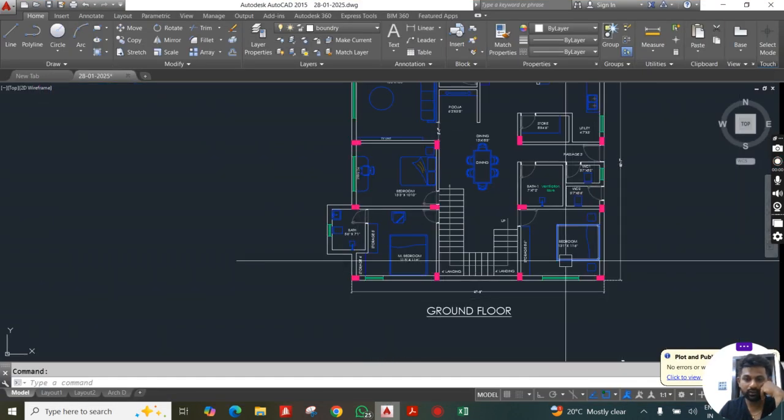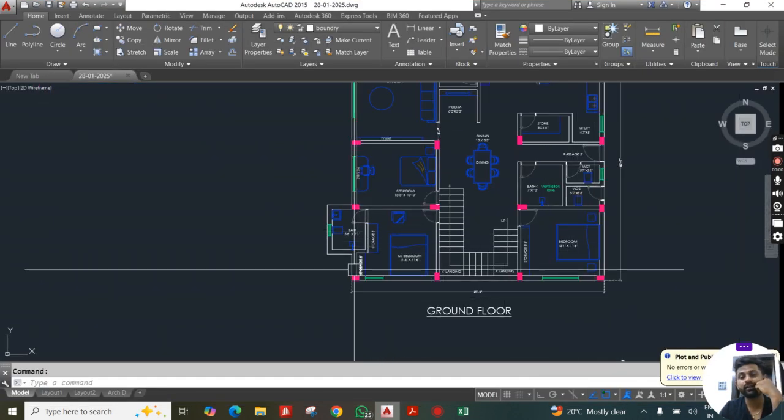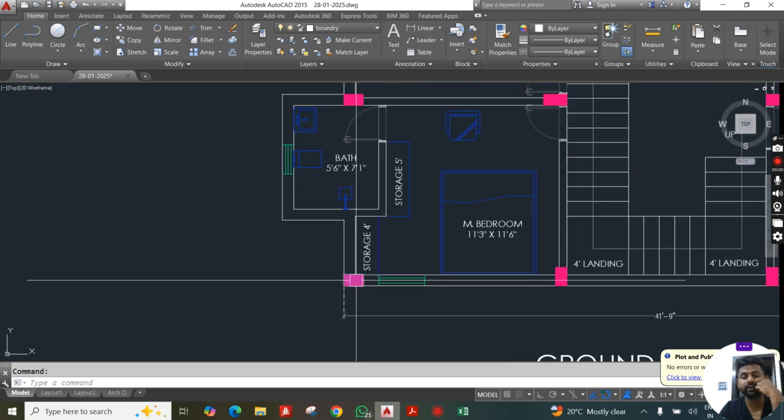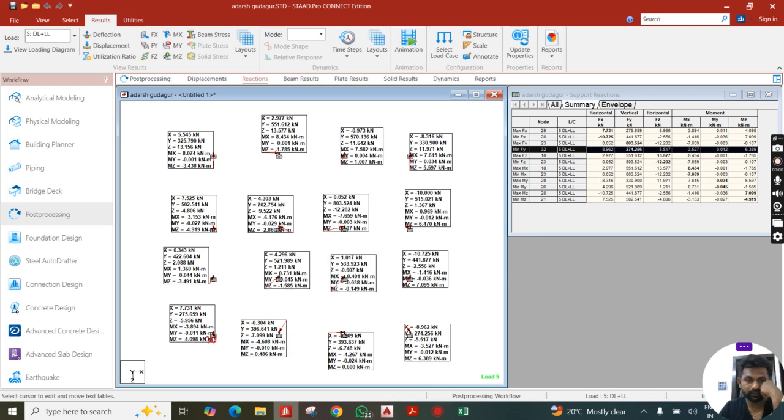If that is 274 and 275, I guess we can go for 12 inches column here rather than 15 inches. And for these four we can still try for 12 inches, and others with 500 will go for 15 inches, and more than that will go for 18 inches.